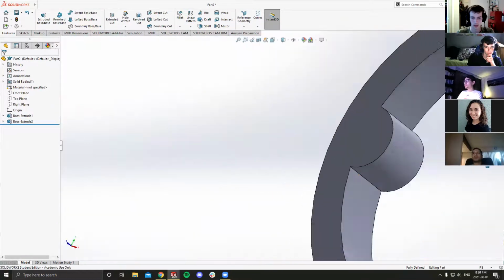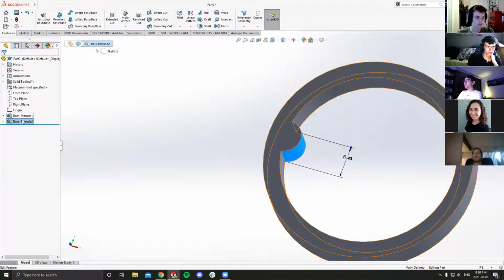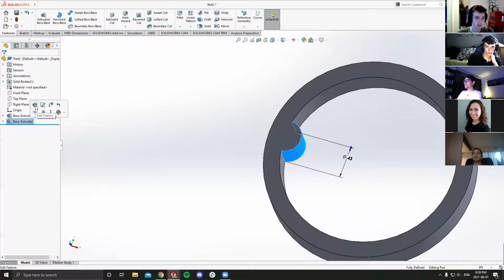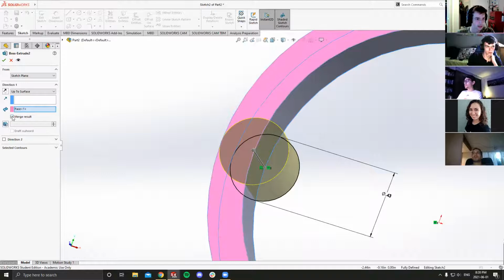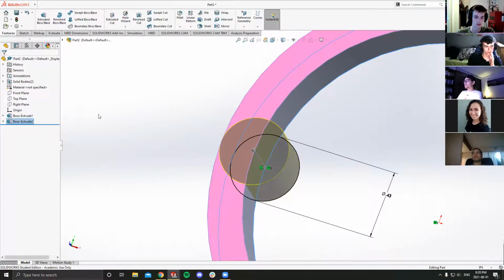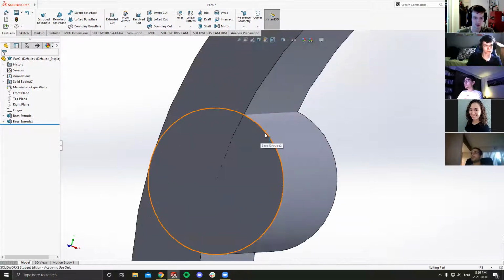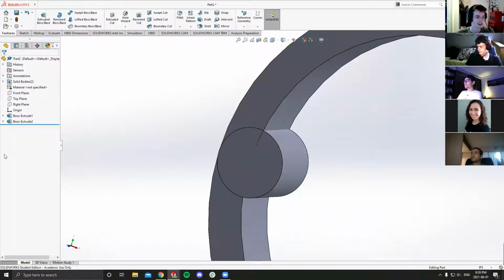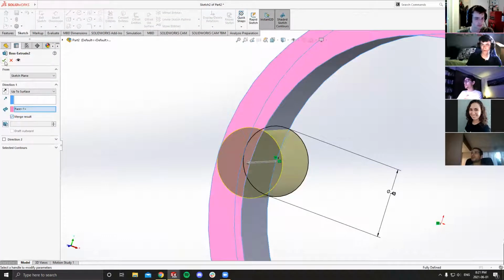Whereas if you boss extruded, you can also edit your features by left clicking on your feature, and then you should get this pop up for your different options. If we edit feature and I didn't press merge result, you can see we get these intersecting faces, which looks kind of gross and is not really what we want. So I'll change that back to merge.